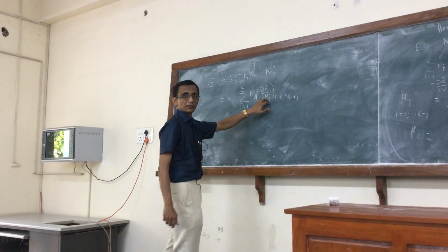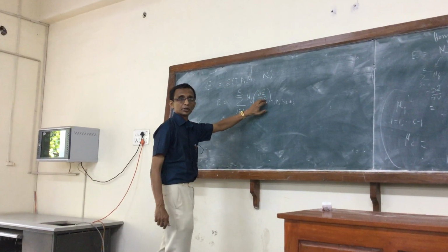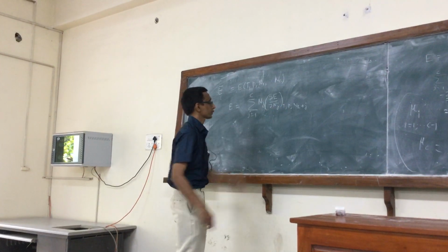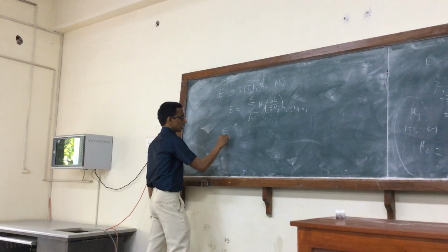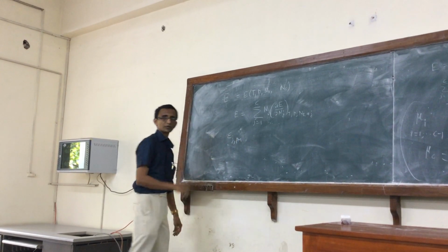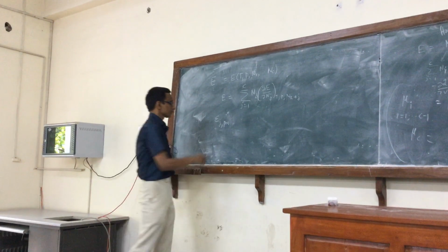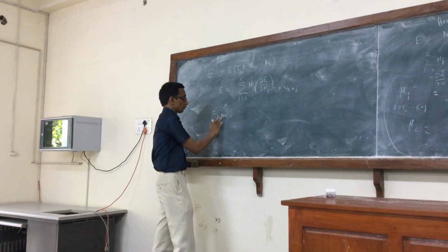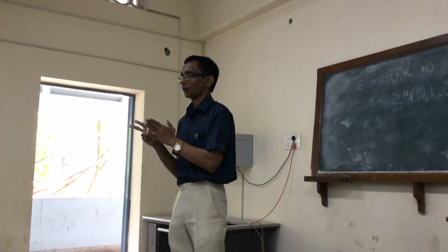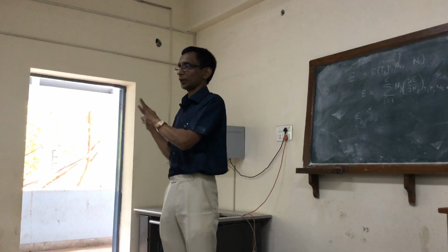now I define this as the partial molar internal energy with respect to component j. There will be C such quantities, so I introduce Ej partial molar. Notation is somewhat different because some books put a bar on top of it. For me, it doesn't suggest anything. So Ej, when I put it, if I don't put anything, Ej would correspond to the pure component j in its pure state, not in the presence of other components, but in its own pure state at a particular temperature and pressure.